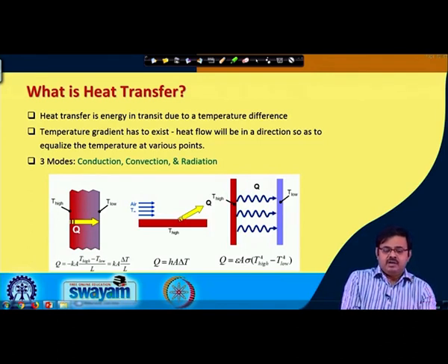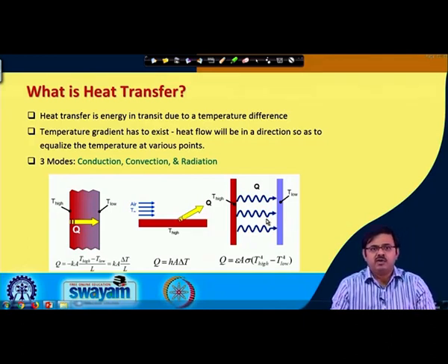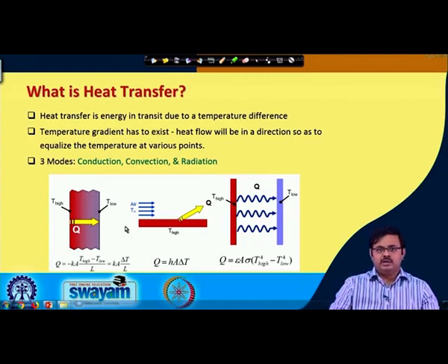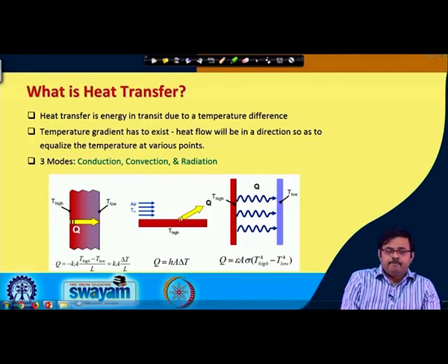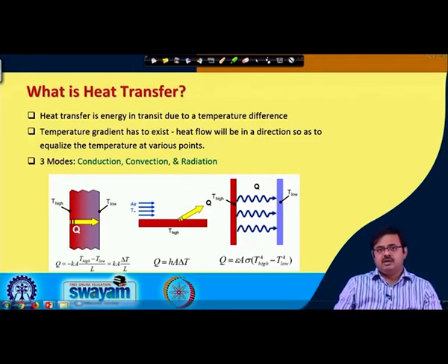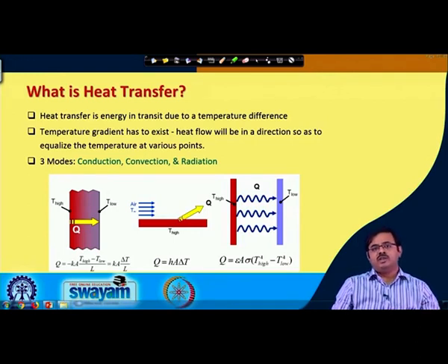For example, I am showing here that air is flowing, and how can this air flow? The air can flow because if I put a fan, let us say at this point, and blow air, or a compressor blowing compressed air, or a pump pumping a liquid, I am doing external work on that, and I have to spend energy to do that, and that is called forced convection, because I am somehow forcing the fluid to flow over this heated surface. So, it is called forced convection.